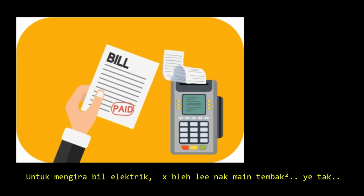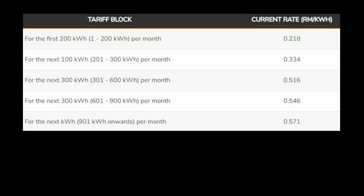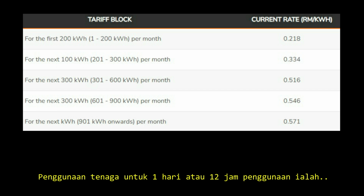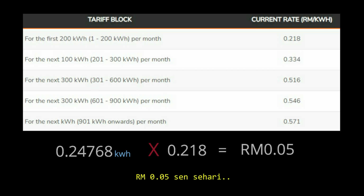To calculate the electricity bill is not just an estimate, but depends on the meter reading following tariff block rates as shown here. To get the cost per day on each block TNB tariff, energy consumption for 1 day or 12 hours is 0.24768 kilowatt-hour, multiplied by tariff at TNB 0.218, equal to RM 0.05 per day.